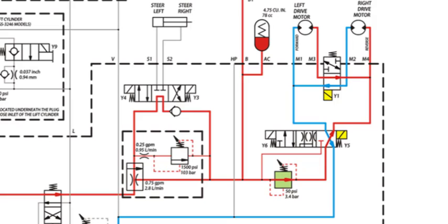As pump flow is connected to both of the drive motors, the oil will follow the path of least resistance. The drive motor which has lost traction will receive all of the pump flow. High drive must be selected in order to recover from a loss of traction condition.